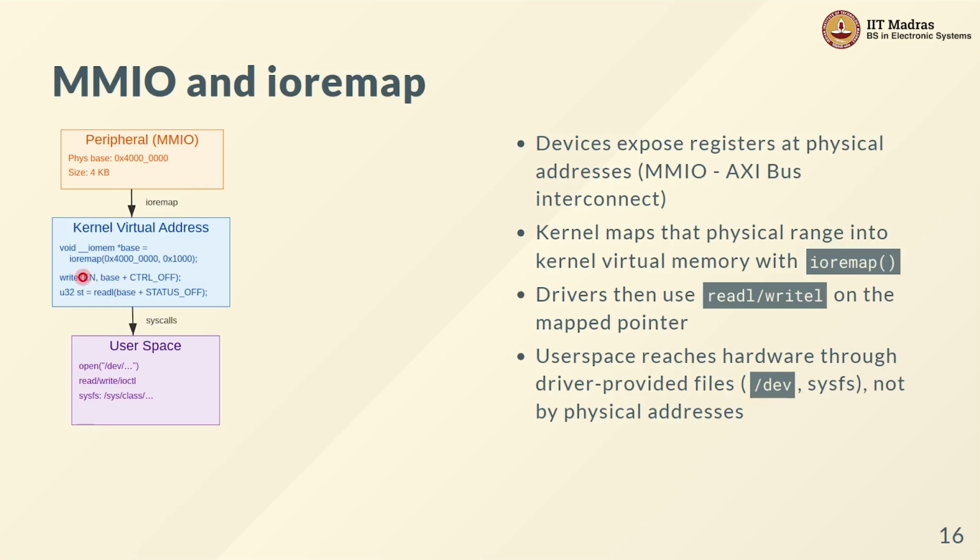allowing the kernel to basically do this mapping, right? And finally ending up writing into this location base plus control offset. So you give the value to be written and you give the address to write it to. And this write-L function will do this mapping between the virtual address and the physical address and write it into the correct location. Okay.